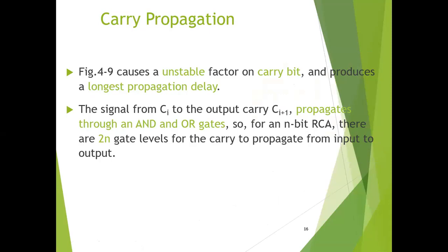However, input carry C3 does not settle to its final value until C2 is available from the previous stage. And we know that similarly C2 has to wait for C1 and so on down to C0. Thus, only after the carry propagates and ripples through all stages will the last output S3 and carry C4 settle to their final correct value, and they have to wait for the previous carries to settle down.